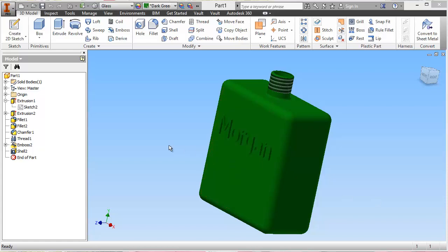Okay, we're very quickly going to have a look at how you can make a lid as well. I'm going to do this a slightly different way. The technique we're going to use is called loft, which is this one here. Now the loft technique could have been used to create the bottle. If you recall the earlier one I showed you, which had sloping edges on it, that was used. I used loft to create that instead of extrude. So it's a similar type technique, but the word loft allows you to do it on an angle, and I'll show you what that means now.